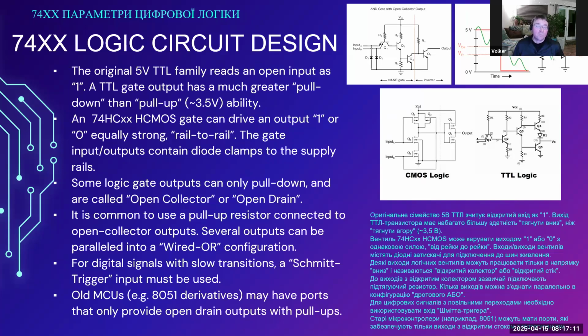In the context of microcontrollers, a lot of microcontrollers will allow for a GPIO port to be configured with a pull-up resistor. Not as many allow for a pull-down resistance ability. It is just not common. The STM32 series does have that capability, but for example, the Atmel AVR family does not. The Atmel AVR family does allow for a GPIO input to be configured with a pull-up resistor, but not a pull-down resistor.